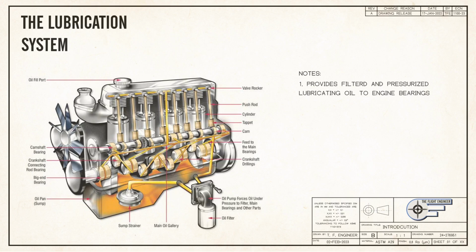The primary job of the lubrication system is to supply cool, clean oil at high pressure to the engine's bearings. Any region of the engine that experiences sliding or rotating contact needs high-pressure oil films to prevent metal-to-metal contact. Without this film, even the most advanced materials would quickly break down under heavy operation. The oil also serves to remove soot and contaminants from the engine, as well as carrying away the heat from friction and combustion.